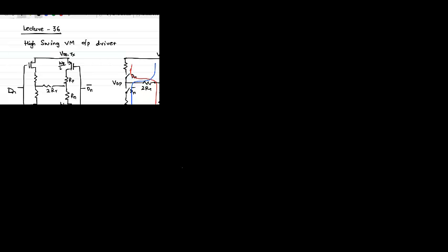then the process variation due to MOSFETs is negligible. Whereas your parasitic capacitance will be much more. So there is a penalty. If you make the MOSFET resistance negligible, then you can very well maintain a 50 ohm termination for these channels across the process variation.